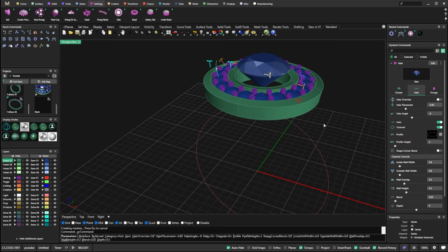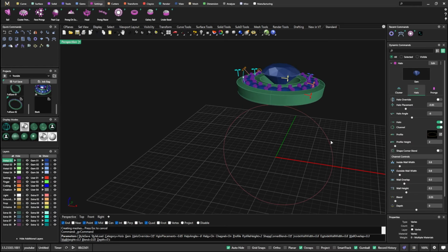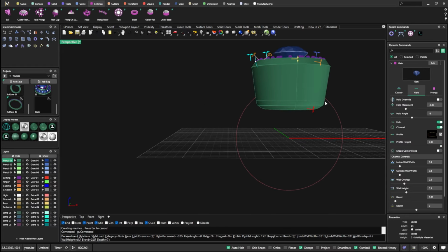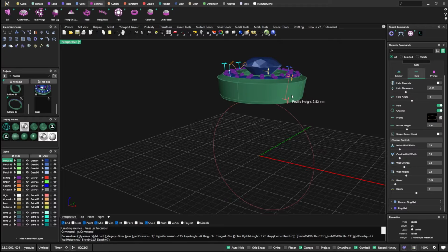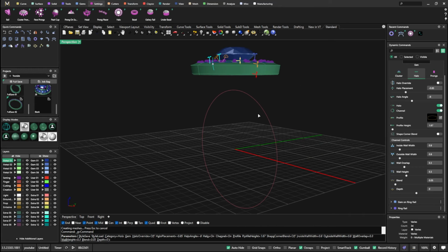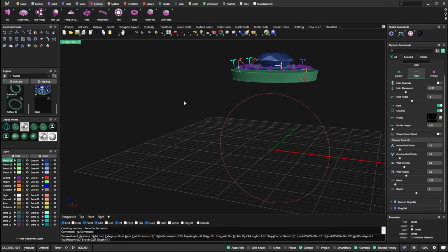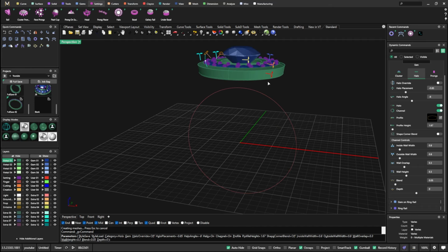That's this one here. Height and depth, how deep we want it, so you can drag it way down so it's in your channel, and then do a ring rail cut, and it'll update everything for you. So there's tons of things you can do with this. Maybe you want the halo up higher, and then you're going to have prongs coming down, or a channel coming in, or some kind of other design going on. You can do that as well.